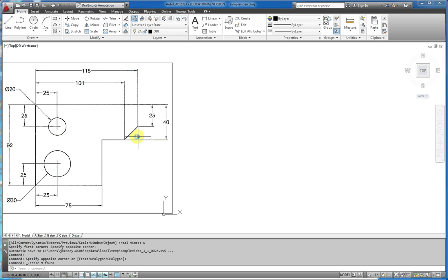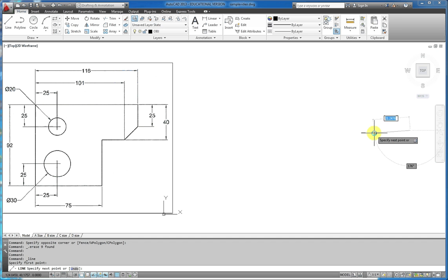So I'm going to start drawing this, and I'm going to pick my line tool, and I'm going to start with this location. So I'm going to come over here in my drawing editor and try to move over somewhere where maybe we'll have enough room to fit this whole thing on here. And so I'll start drawing right here. So I'll left click to start my line, and right now I've got my dynamic inputs turned on. That's what you see, the numbers that are highlighted there with the distance and the angle.